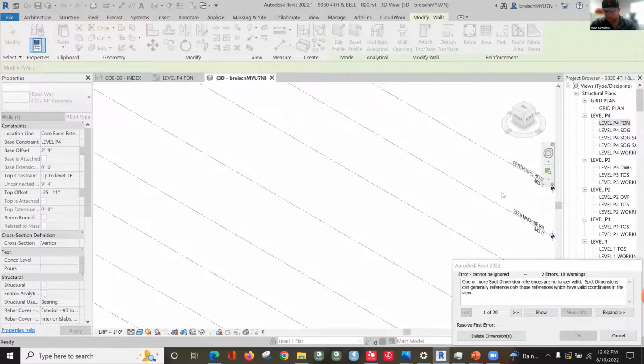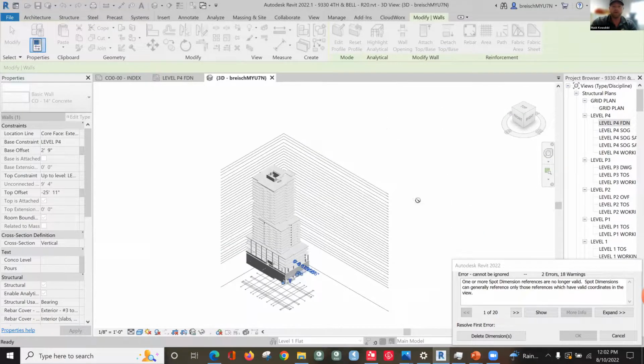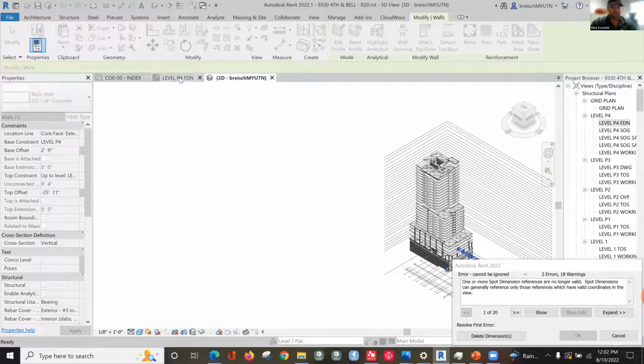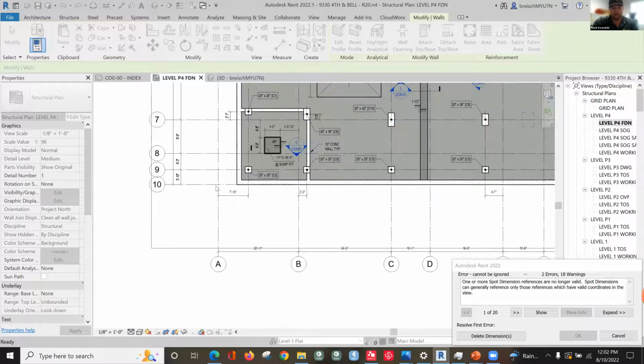It's a couple of floors down below ground and 32 floors above ground. Typically you'll see this when you first open it up, depending on the size. This one's the bottom level. What this workflow entails is changing your coordinate system at this point. The reason you do this is that when I go to export an IFC or DWG or anything from here, it will then be on that coordinate system.